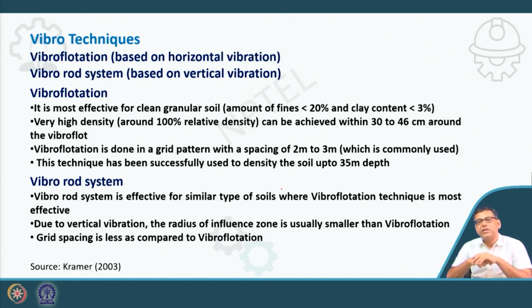Around 30 to 46 centimeter of the vibro float laterally, because here we are providing a horizontal vibration. Vibro flotation is done in a grid pattern with spacing of say 2 to 3 meter. That means we apply these techniques in a grid pattern.